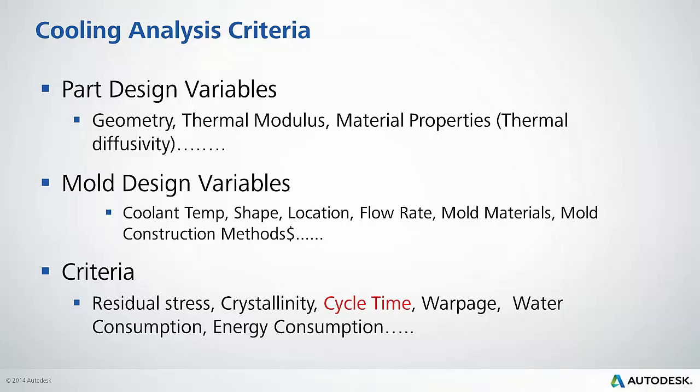that window that we provide, say interior, right, for the heat to pass. Is it a sharp corner? Is it a generous radius at the corners? Heat flow through those corners, corner effects will be different based on the geometry. So it's something like a term that I used with simulating investment casting, thermal modulus, too, right? So surface area to volume ratios also can be looked at in this part-only mode, as well as thermal properties.